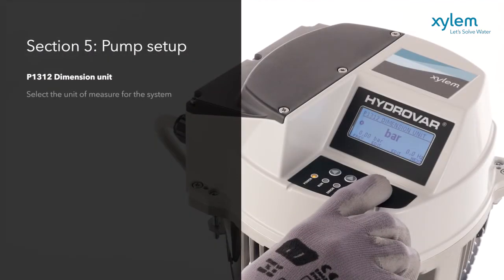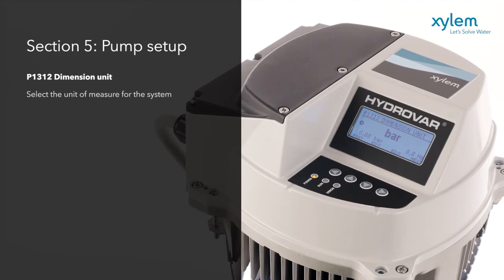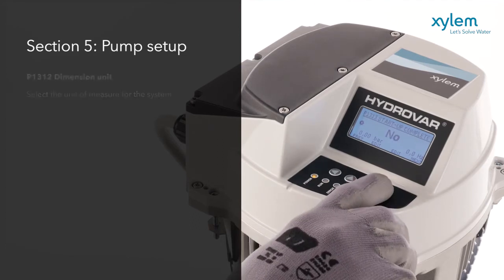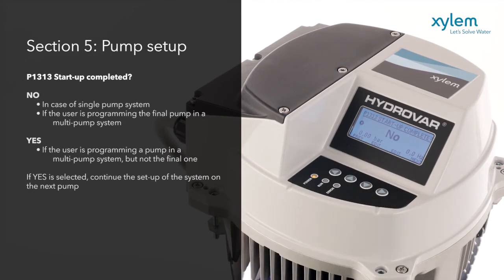Then set the unit of measurement for the system. In a multiple pump system, the procedure can be stopped at this point on all pumps except the final one by selecting Yes, and then completing the procedure on that final pump by selecting No.